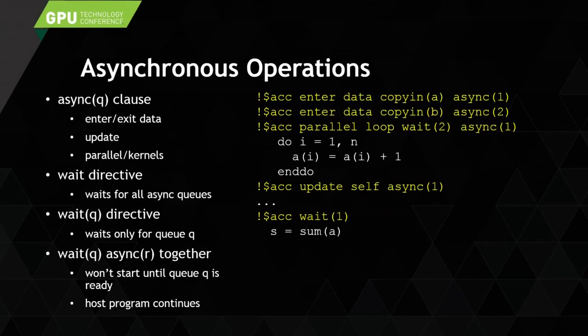And I don't want the host to wait. Right? One thing to do is just have the host wait until they're both finished, and then put this guy on the queue. But I don't want to have the host wait. So what I'm going to do is put on this queue, wait for that guy to finish, and then this thing here. So these things will kind of flutter down. Then the wait gets here and it says, well, is he done? And if not, I wait until he's done. And then let the next one go on. But meanwhile, the CPU is able to continue, and all that time, the CPU has gone on to do other things. The point is the CPU is not waiting. The queue has a wait on it, so that's done in the hardware on the device.